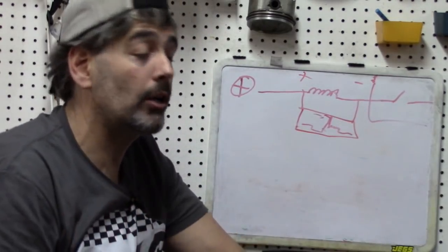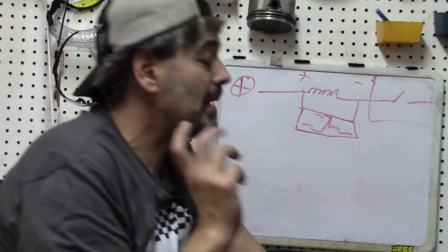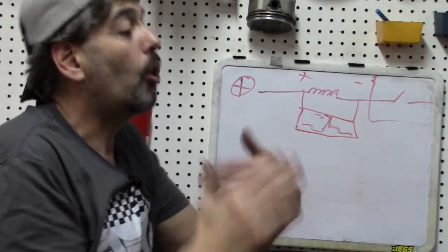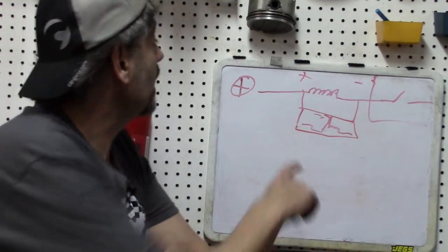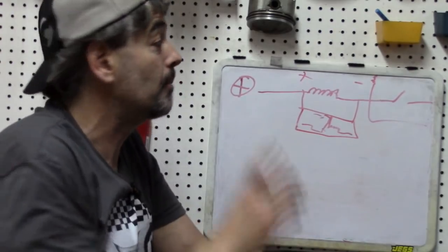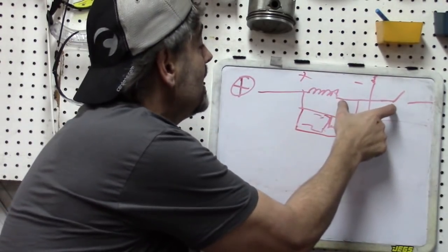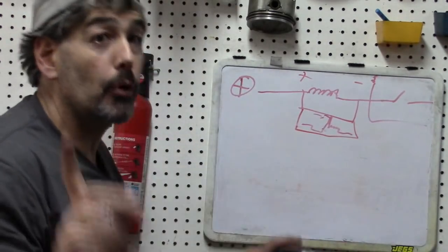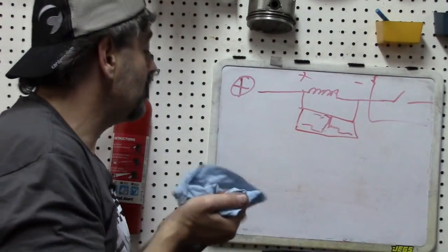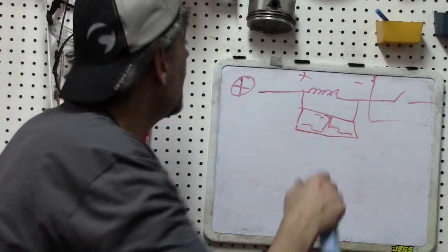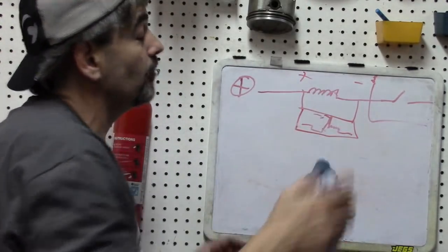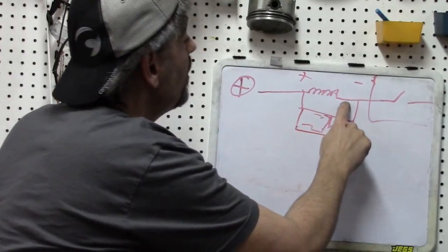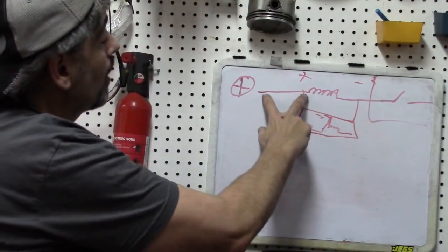That is a critical thing to understand, because when we look at our 3 and 4 wire systems, hopefully it's going to become clear to you when I draw out the 3 and 4 wire system why that is a critical phenomenon. What I want to do is first prove this to you by bringing back in my 2-wire model, and we're going to show you that the voltage spike phenomenon is actually only on this side of the circuit, not on this side.